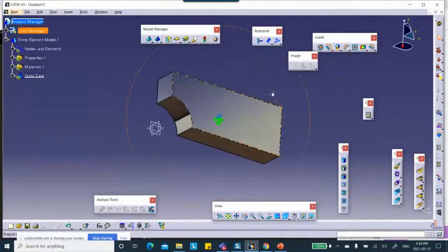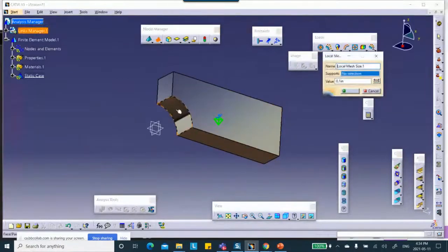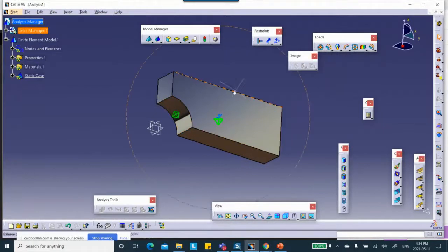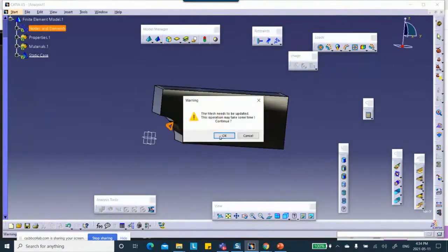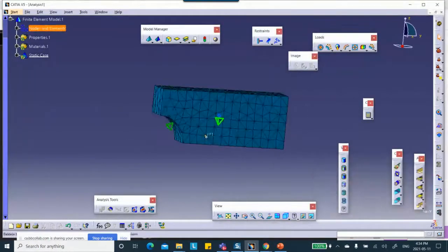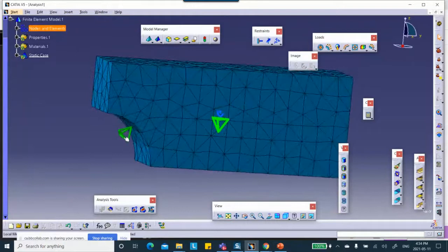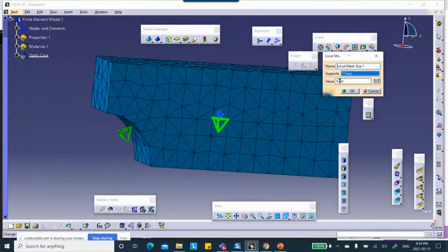Let's do some local mesh refinement here. I like it. So here, but I'm not going to use the same number. This was too small. So we make it, I don't know, 0.3 maybe. Yeah, it's more respectable. It's still smaller than that. Okay. And you look at your mesh. That actually doesn't show that much. How about 0.05?